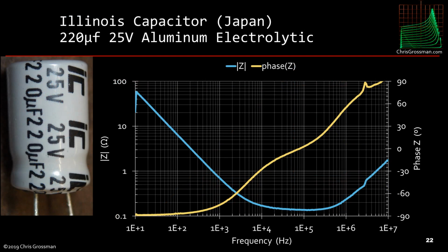So now let's look, here's an example of a measured electrolytic capacitor, the 220 microfarad 25 volts. Here we see this glitch right at the beginning of the plot, and this is kind of a glitch in the Siglent Bode Plot software, or firmware in the scope. It's fine during the first sweep, and then it'll screw up this first point, and on the subsequent sweeps sometimes it'll go back. It's not a huge deal, but it is a little annoying.